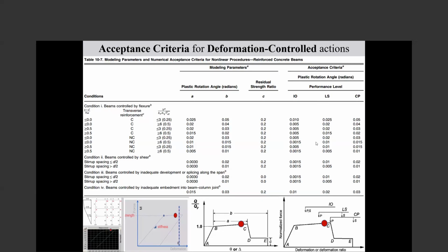You want the concrete section, beam, column, arrangement of reinforcement. So based on the arrangement of reinforcement in column 1, rho minus rho prime divided by rho balance, you see which row you are in, and based on the transverse reinforcement in the second column, and based on the value of the shear third, then you have your curve. Those A, B, C are the values of the curve.